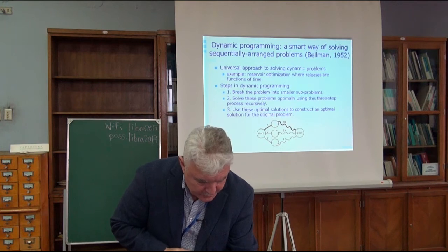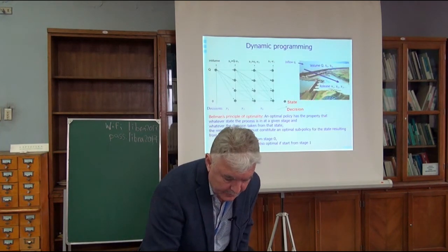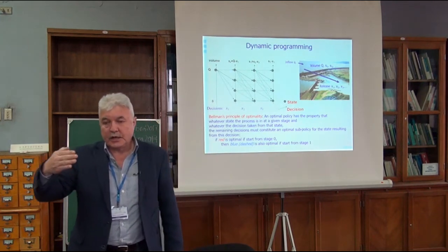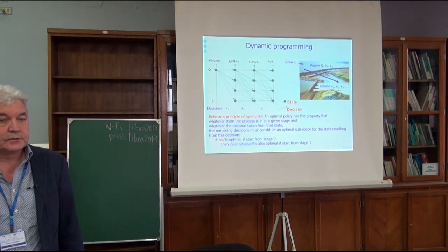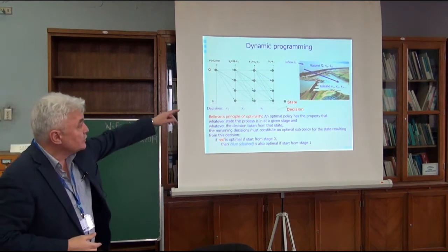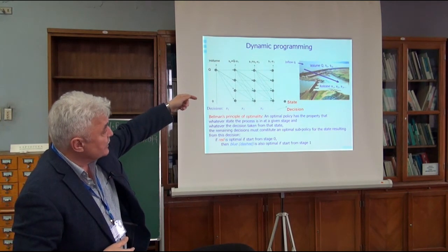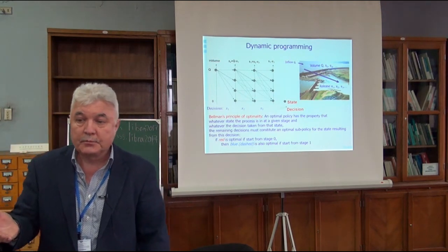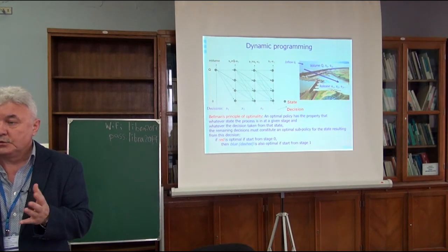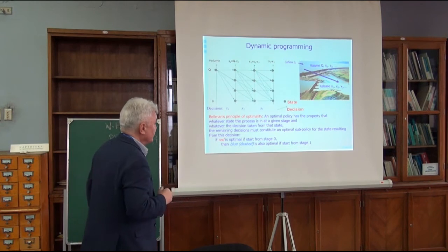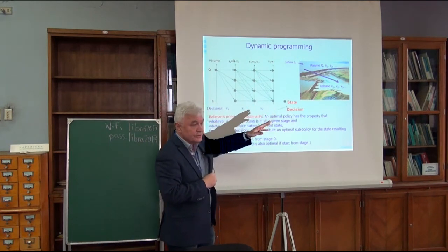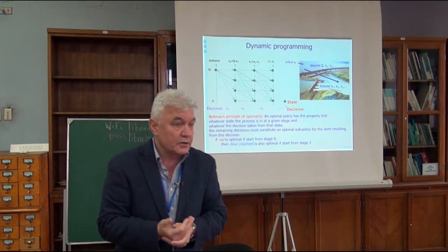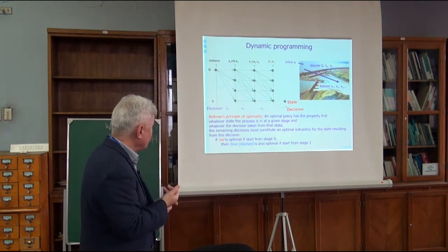Optimization of water systems. One of the interesting problems is optimization of reservoir releases. Releases are how much water you release through the turbines or simply release into the river. On the left-hand side, you have a reservoir, and it has a certain volume, and the volume changes in time. And you have inflow, by the way. So forecasting inflow is an interesting problem. How much water comes into the reservoir from different sources, you have to know, also when building it, but also when operating it. So optimization here is to find releases such that your reservoir would work well. What does it mean? Well, for example, producing a lot of hydropower generation, but not only.